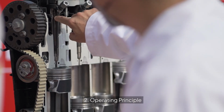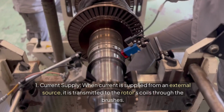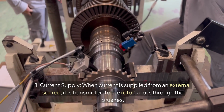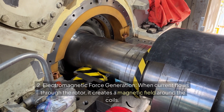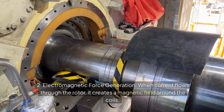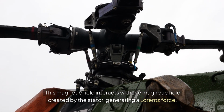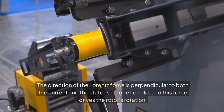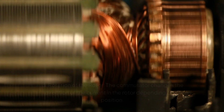2. Operating principle. The operation of a DC motor involves the following steps. 1. Current supply. When current is supplied from an external source, it is transmitted to the rotor's coils through the brushes. 2. Electromagnetic force generation. When current flows through the rotor, it creates a magnetic field around the coils. This magnetic field interacts with the magnetic field created by the stator, generating a Lorentz force. The direction of the Lorentz force is perpendicular to both the current and the stator's magnetic field, and this force drives the rotor's rotation.